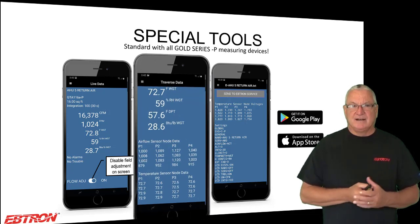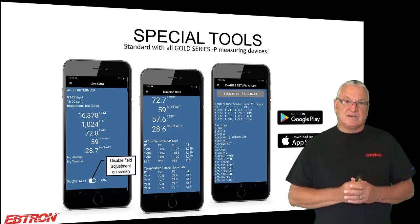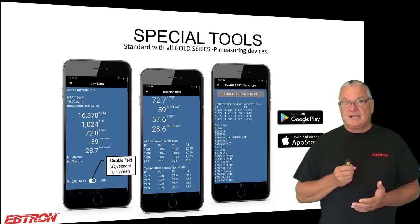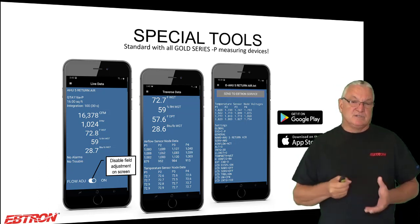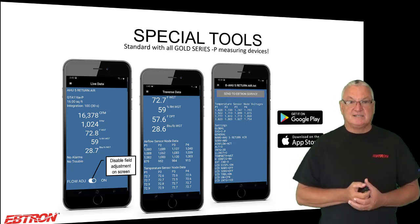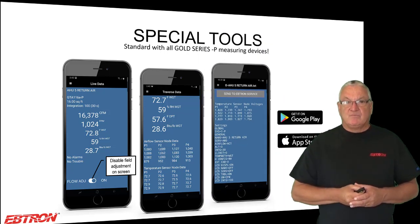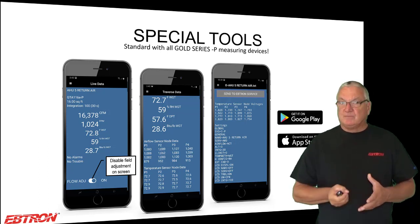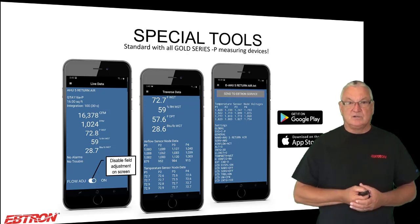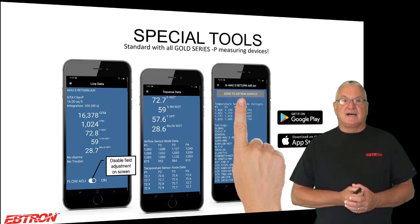That second screen in there has traverse data. This option was originally developed for test and balance people. It gives you individual airflow rates as well as individual temperatures of each individual sensor node. Very valuable to balancers, but it's also very valuable to anybody that wants to do some diagnostics on their system, see what's going on. And then we have basically a full diagnostics menu. It tells us basically everything there is about the transmitter, what all the configurations are set to, any active trouble codes, historical trouble codes. And the cool thing there is if you do have any trouble, it has that little send to Ebtron service. You just click on that and it will send it off.